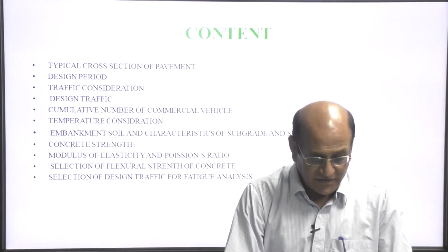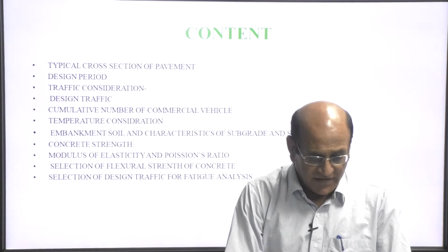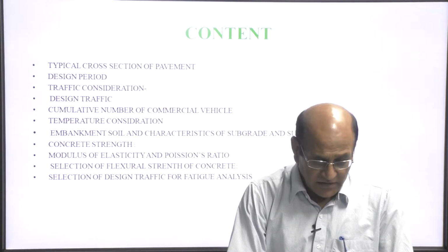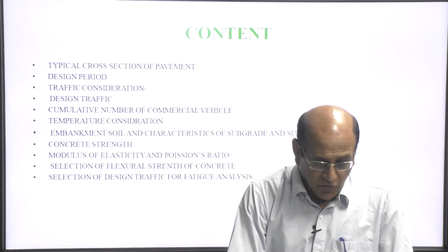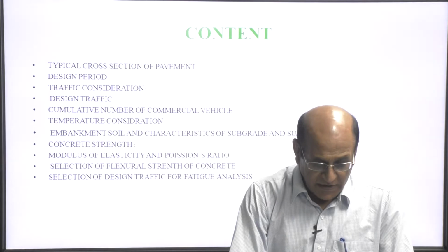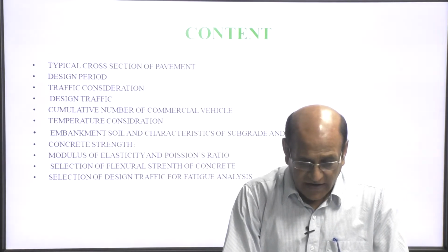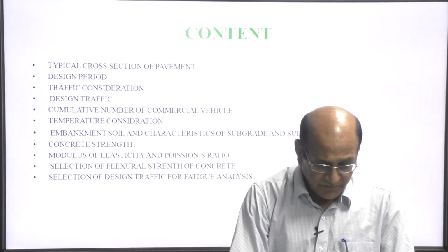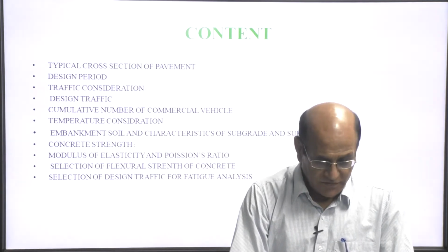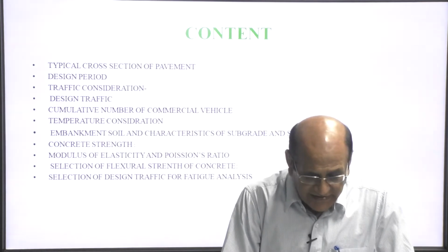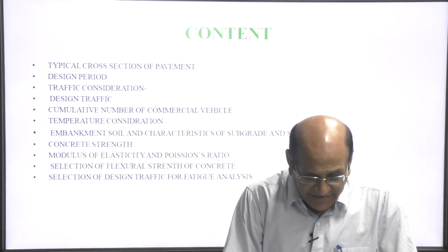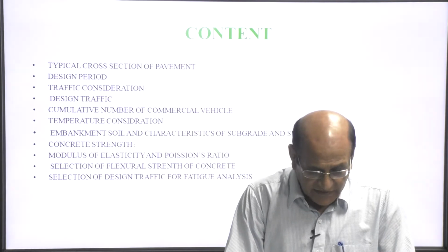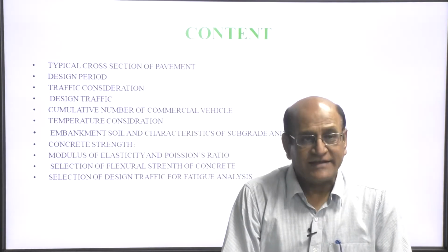Contents of this lecture: typical cross section of the pavement, design period, traffic consideration, design traffic, cumulative number of commercial vehicles, temperature consideration, embankment soil and characteristics of subgrade and subbase, concrete strength, modulus of elasticity and Poisson's ratio, selection of flexural strength of concrete, selection of design traffic for fatigue analysis.